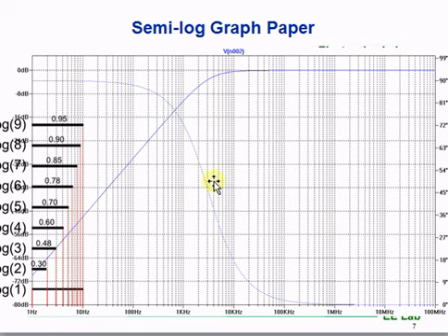Your drawings will resemble this graph. You can see, since it is a high-pass filter, the signal will not degrade in high frequencies, but it degrades very fast in lower frequencies. Note that the figure shown here is drawn in dB scale.